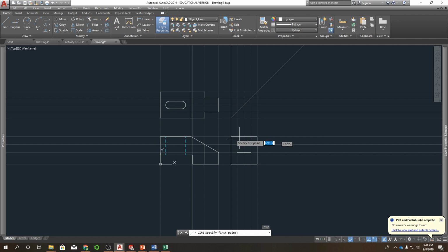Now this line goes from here to here. So shooting over the miter line, down, over there, and there. That's this edge, which comes here, there. We can actually just shoot that down because it comes to here and then goes down again. So instead of having a bunch of line segments, I would tend to just use this solid line. And as you can see now, we have this T shape also in the right view.